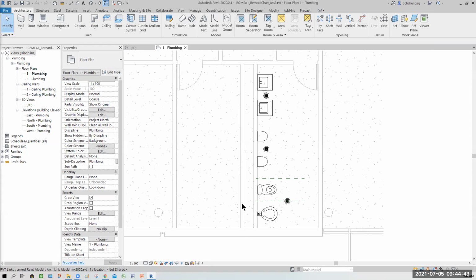Of course, they have more, and because sanitary is built via gravity, there's a sloping percent. So I was told by the industry, when I teach them, they told me it's around 1 meter to 9 meter. That means the slope percent. So when you prepare this, you can take that as the calculation, 1 versus 9. All right, so from there, you have the slope percent.